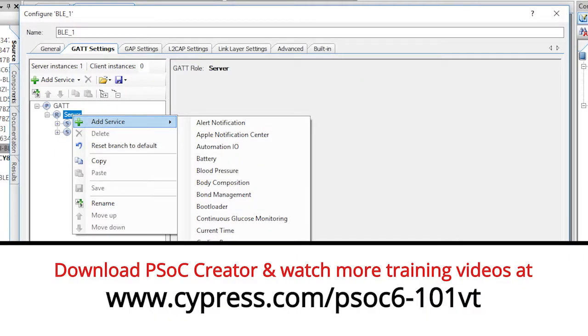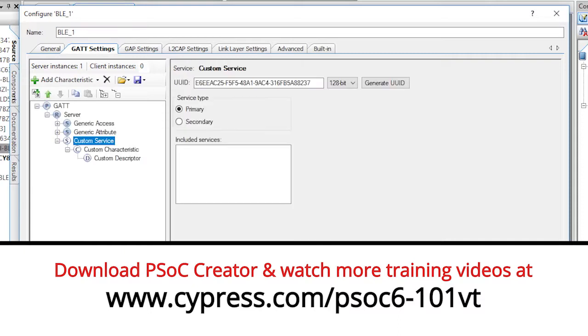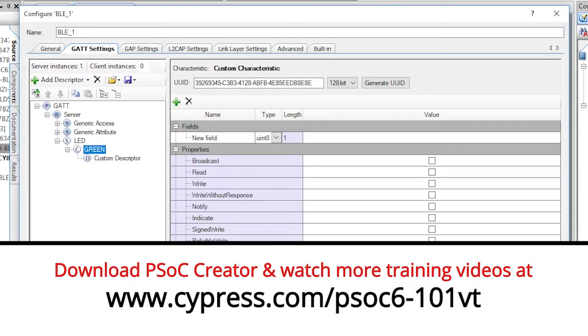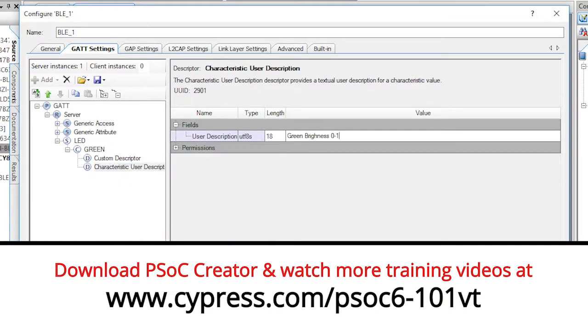In the previous lessons, I showed you how to build BLE peripherals, specifically a peripheral running the immediate alert service and a peripheral running the custom service. In those lessons, we used your cell phone to talk to those devices. In this lesson, I'm going to show you how to create the other side of the connection. The other side is more properly called the central, or more specifically, the GAP central.